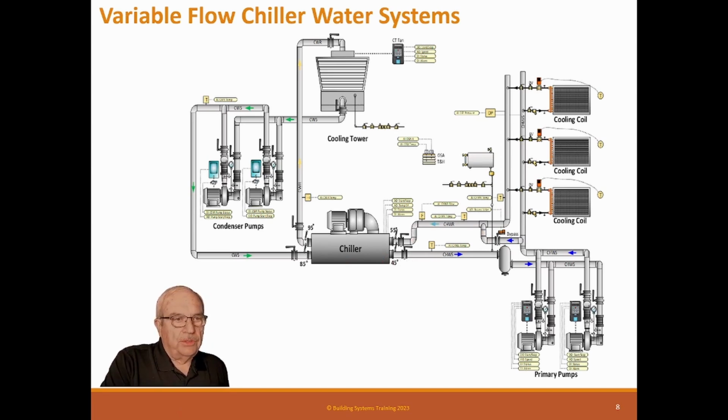So originally, we tried to control this valve under pressure with chiller pressure. Doesn't work at all. Please don't let them do that. The best way is with a flow meter. I put a flow meter in this pipe, and that flow meter will control this valve directly, and those work great. That works fine. Doing pressures is a headache. You just can't seem to get it to work. And once you get it to work, something changes. I mean, a blip of air in the chiller bundle will drive the pressure sensor crazy, or else a little scaling in the chiller bundle drives it all crazy. So you really need a flow meter to run those. That's a design issue, but one we found.